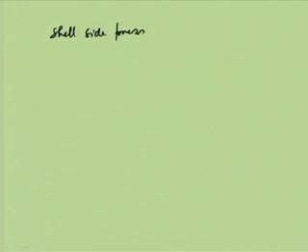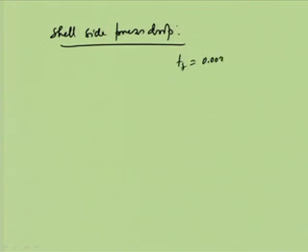pressure drop, again using the same relationship, FF equal to 0.0035 plus 0.264 by RE to the power 0.42, and all RE and these things are known to us.